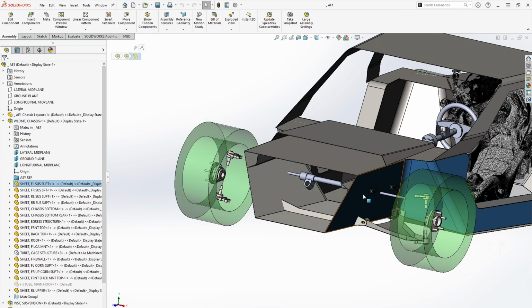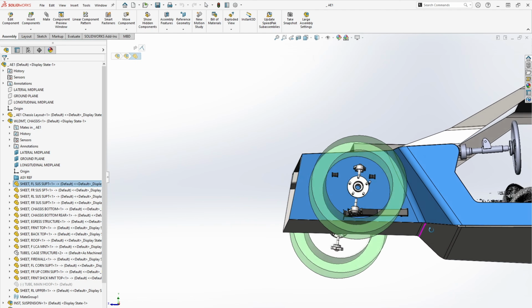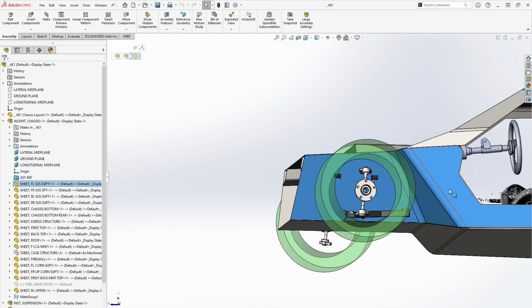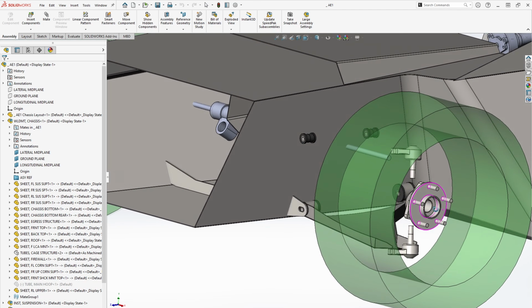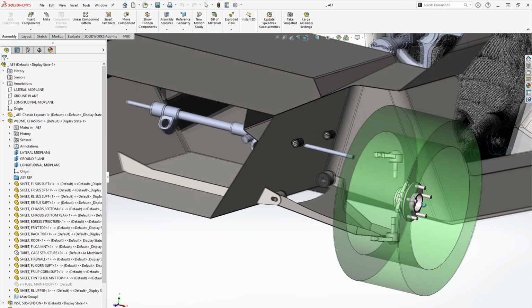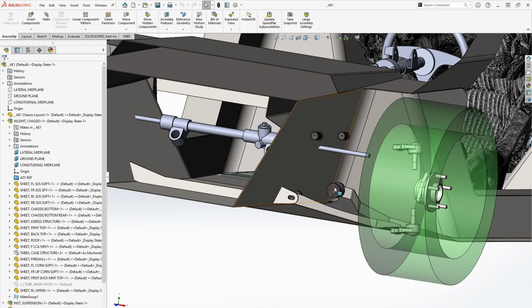What I've been able to do is take this suspension support, wrap it around this inner lower control arm joint, and then swing it around to help create that driver envelope. You can see I've got my wheel bearings all picked out. Those are models I've created based on the ones that I have on the shelf already. Same thing with my upper and lower ball joints.